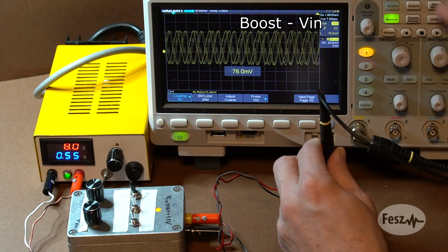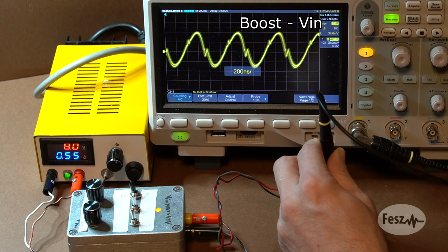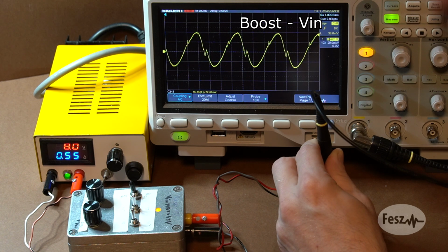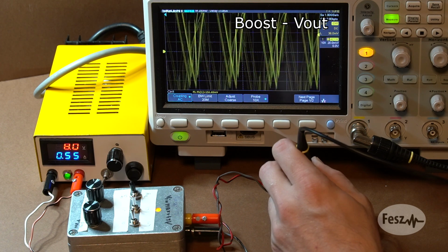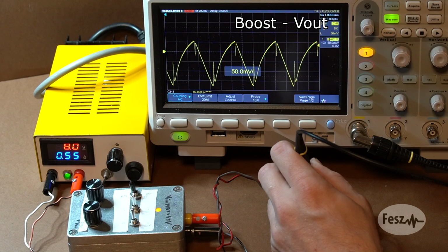Leaving this aside for a moment, if you look closely, you will find noise in other parts of the circuit as well, like the input and the output. The noise is much smaller, we are talking millivolts here, but this is a bit more problematic since this noise is conducted by our conductors to all the other circuits to which the converter is connected.